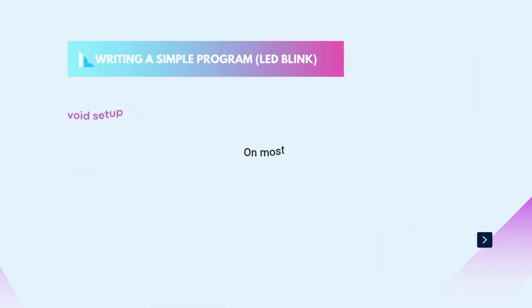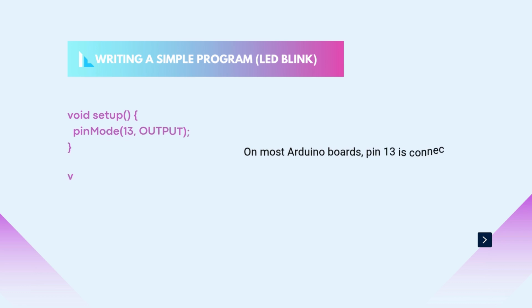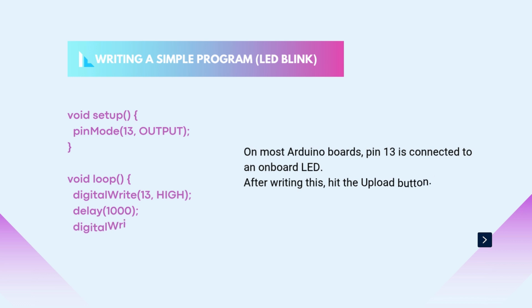Let's write your first program, blinking an LED. On most Arduino boards, pin 13 is connected to an onboard LED. Here's how we blink it on and off every second. After writing this, hit the upload button. You'll see the LED start blinking.